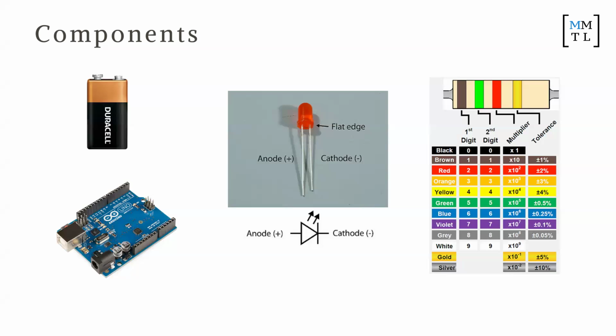There's only 3 different kinds here. So remember to put in a resistor, we'll talk about this later. But if you just have an LED, it will break, because it's going to snap, and we'll talk about why. So make sure you have all these 3 components: a resistor that is 330 ohms, so make sure that it's 330, an LED, and an Arduino.